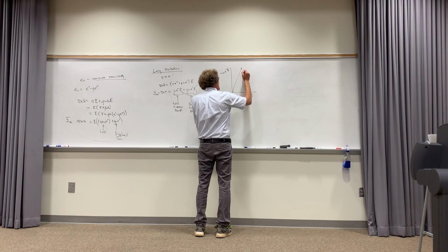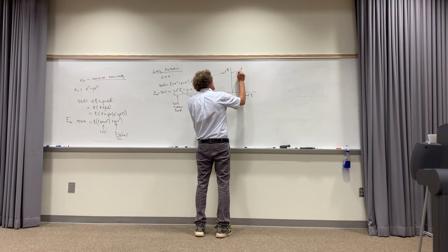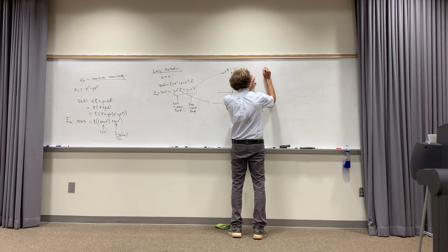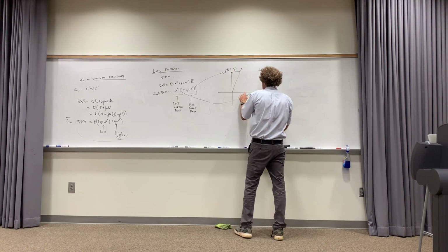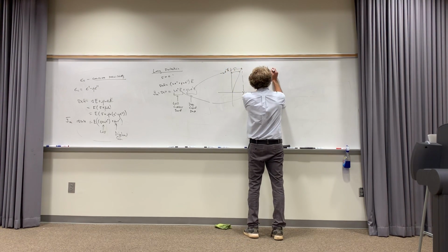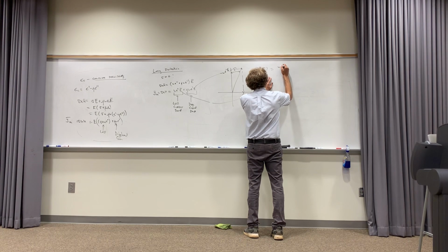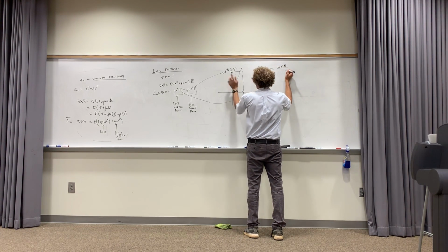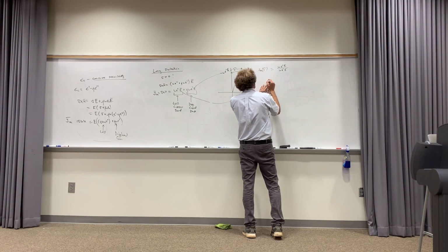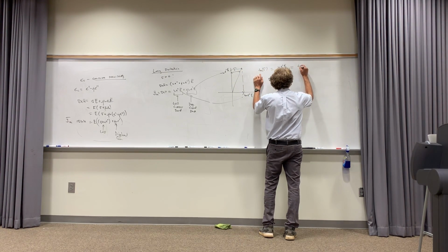And you'll see something like this. You're going to see that there's an angle here. And if you look at the tangent of that angle, it's the opposite over the adjacent: omega epsilon double prime times E over omega epsilon prime times E. By the way, this is called the loss tangent.